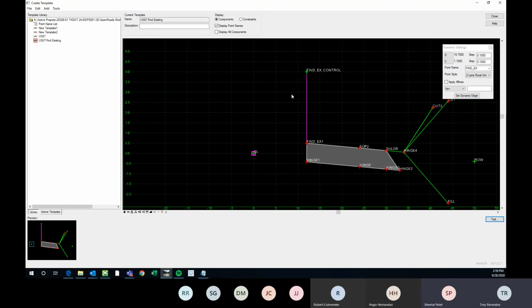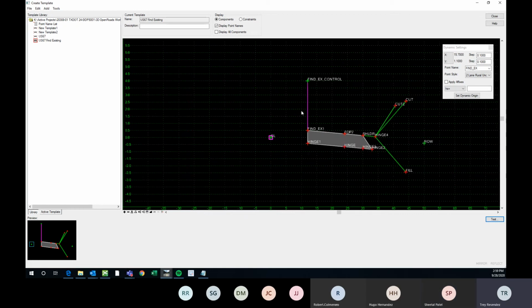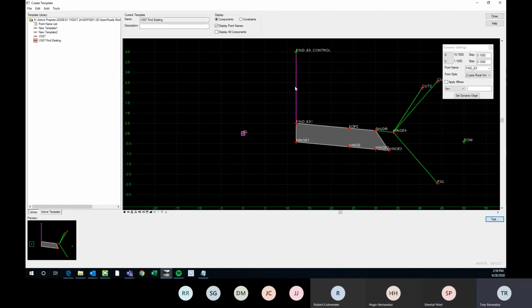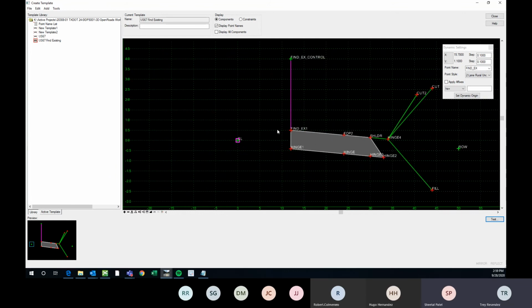I think it would be fine to do that as long as we have the super elevations for the curves, right? Because it's not always going to be crowned. Yeah, we're going to have to add super elevation to the curved sections. But I think this will definitely work for that. Okay, just was wondering.